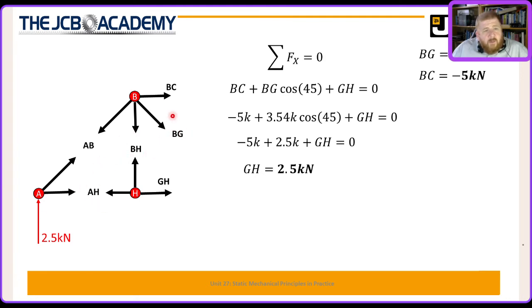So if we're coming through to CD, EF, starting at point A, then we've got 4 or 5 different lots of rounding errors all cooking into the problem, making our values slightly less accurate. Whereas if we use the method of sections to work out BC, and we literally start with BC, then there's only the rounding of BG and the rounding of GH that go into making BC. We've got 1 section of rounding errors, so we are more accurate.